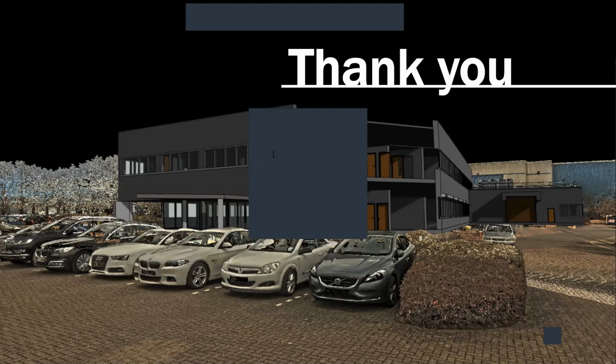Okay, that's good. Laser scanner. The thing is, we don't have a drone mounted laser scanner. With drones, we have a survey grade photogrammetry module, which allows you to get point clouds based on photogrammetry. And you can use it on an offshore facility on water. That's not an issue. Or scanners like the BLK 360 and RTC 360 can be carried to an offshore site, and then you can do a scan there. The RTC 360 comes with an onboard GNSS receiver, and you can also use your GPS receivers to geo-reference the data offshore. So this data can be achieved.